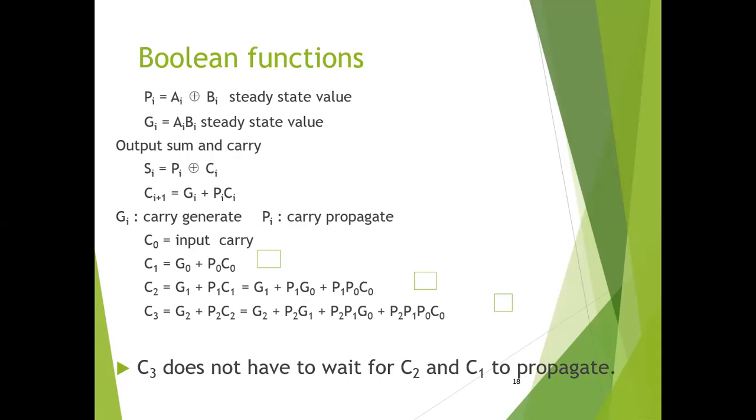Although the adder, or for that matter any combinational circuit, will always have some value at its output terminals, the outputs will not be correct unless the signals are given enough time to propagate through the gates connected from the inputs to the output. So the output will not be correct unless the proper propagation time is given to the gates to process through the combinational circuit. Since all other arithmetic operations are implemented by successive addition, the time consumed during the addition process is critical.